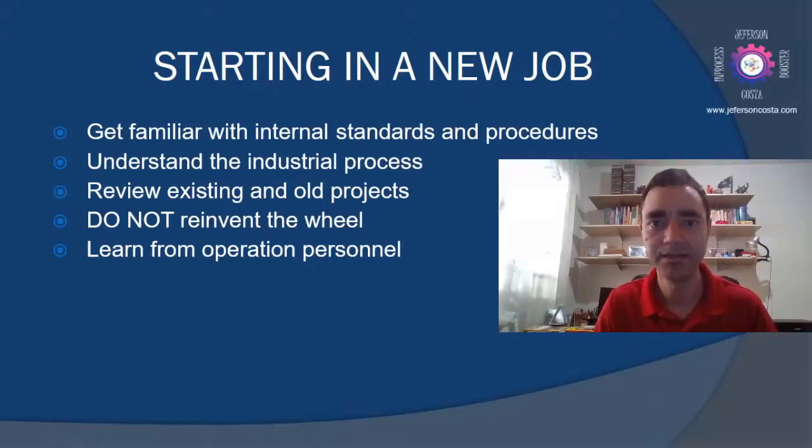This is the kind of issue that, when you go to the field and talk to operations, or when you participate in the problems, you take it with you, and the next time you do a pipe instrumentation diagram, you will add a note to not install the valve in the vertical position, for instance.